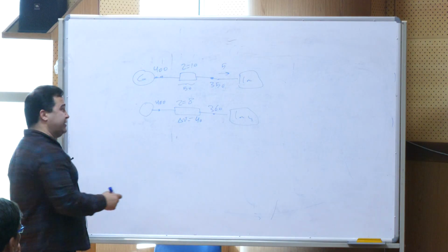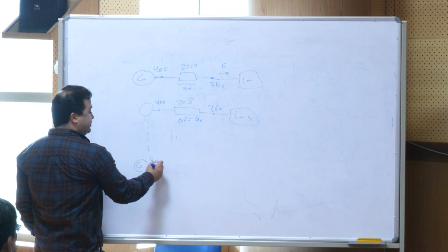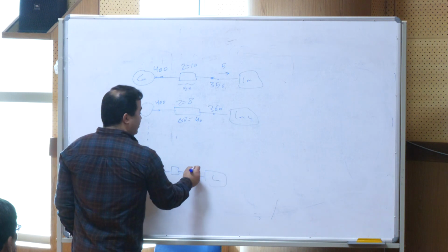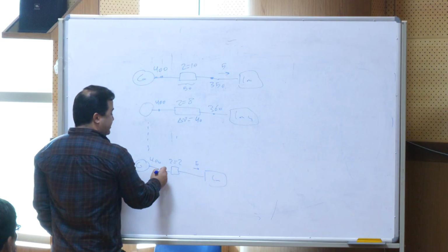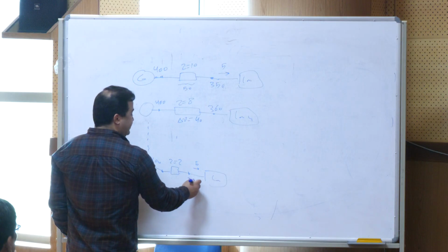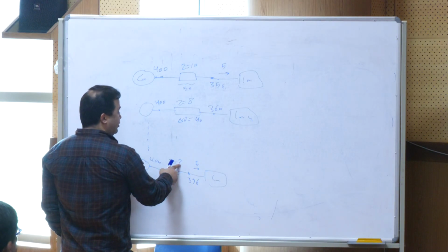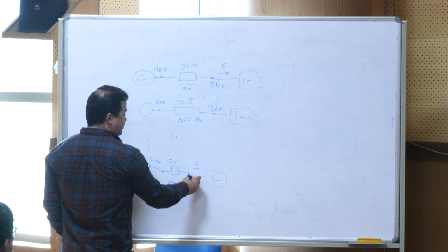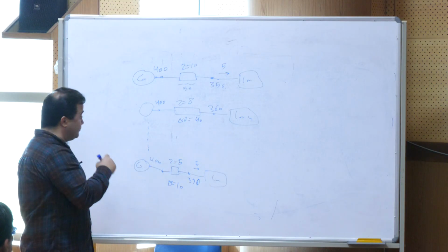Then we go to the same grid, 400, and then we have a load, current is 5, Z is 2. So you see that this is 400 and this is 396, and delta V is equal to, sorry, current is 5, Z is 2, so it is 10.